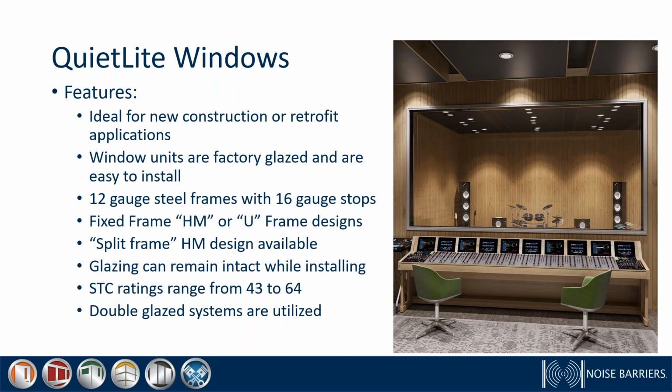Here's another great product that I definitely like. I've personally had the pleasure and the opportunity to put these in the field. Quiet light windows tested very well in the test lab, and also test very well in the field. The frame itself is 12 gauge metal, so it's a very stout frame, and it comes with 16 gauge stops.